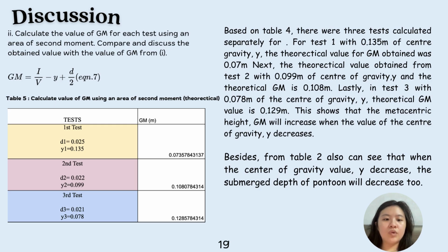We found this relationship: when the center of gravity Y decreases, the metacentric height GM will increase. And we also found that when the center of gravity increases, the submerged depth will also increase.